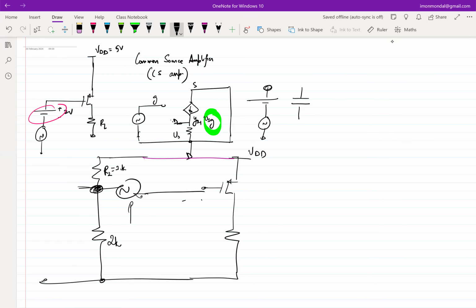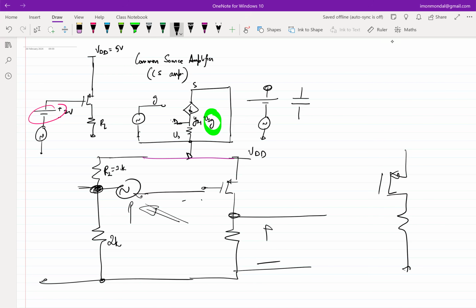It's probably the previous stage amplifier output. For example, let's say this is this, and this has to go into the gate of the second stage. Then you cannot obviously put this voltage in series, isn't it? Because you have access to only one terminal. And this is more of a practical problem also, because normally you always use multiple amplifiers, one cascaded with another, then you cannot do that. So even though this seems like a very nice solution, it's a practical problem. You cannot use floating sources.